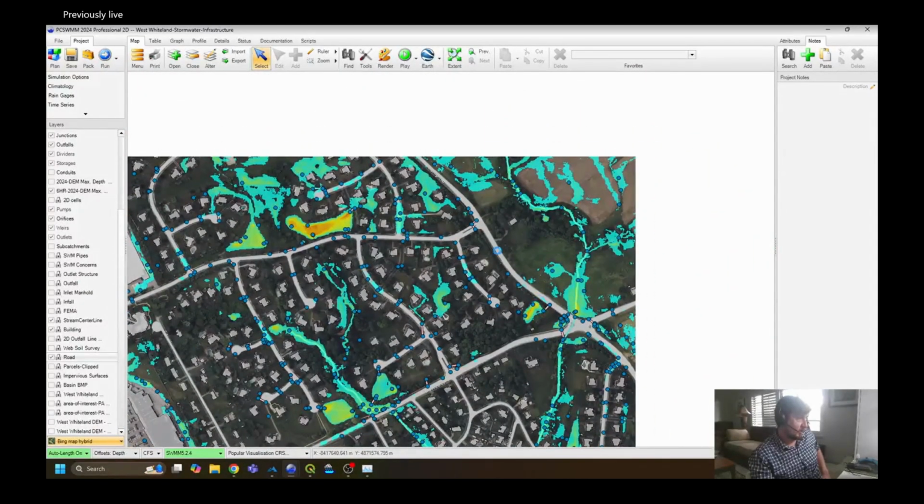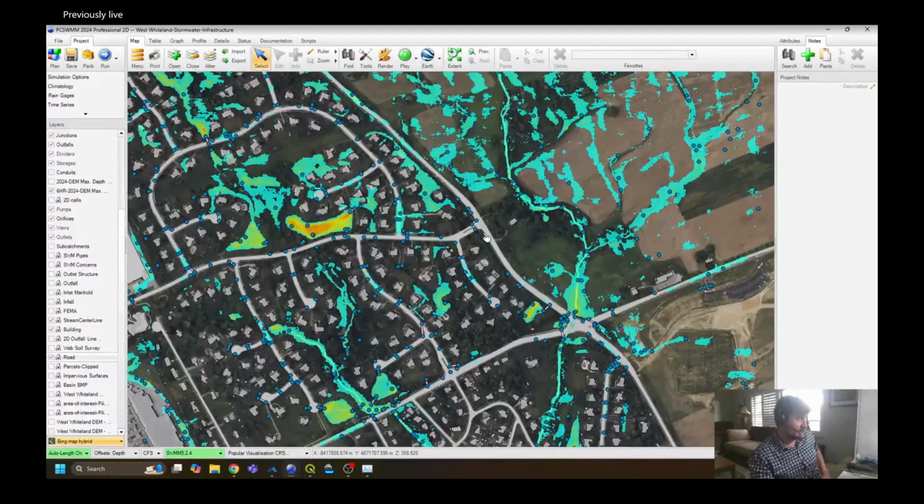And then I can use that when I have my mesh generation. Instead of me drawing out everything, like I did in my workflow with HEC-RAS, I can actually use my GIS polygons and say, hey, give my road a different type of polygon, give my road a different type of Manning's roughness so that water can flow more like a directional flow path.